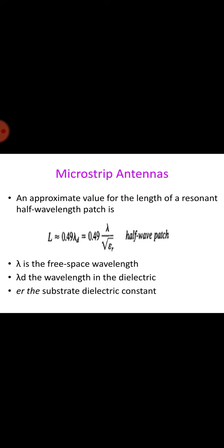In the standing wave mode, the half wavelength separation between ends leads to electric fields that are of opposite phase on the left and right halves. Therefore the total fringing fields at the edges are 180 degrees out of phase and equal in magnitude. Viewed from the top, the x components of the fringing fields are actually in phase, leading to a broadside radiation pattern, that is, the peak radiation is in the z direction.